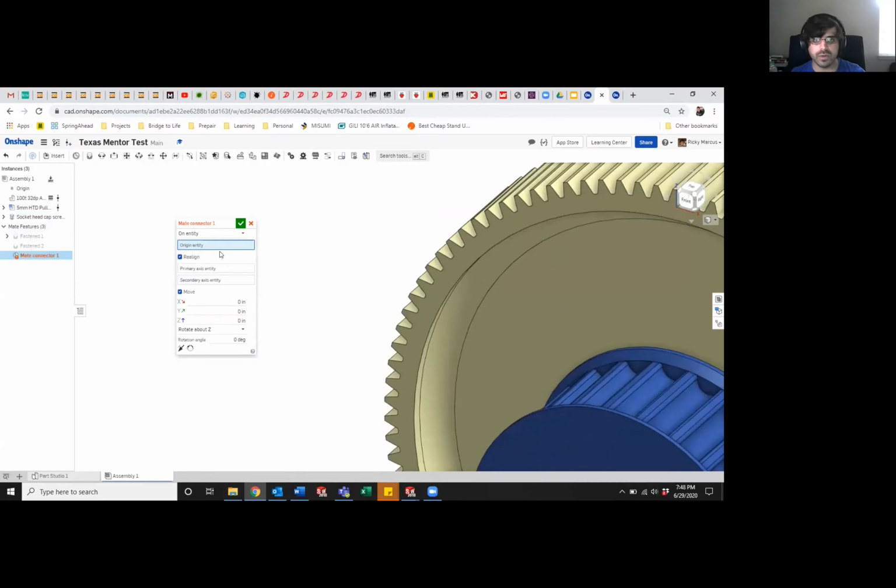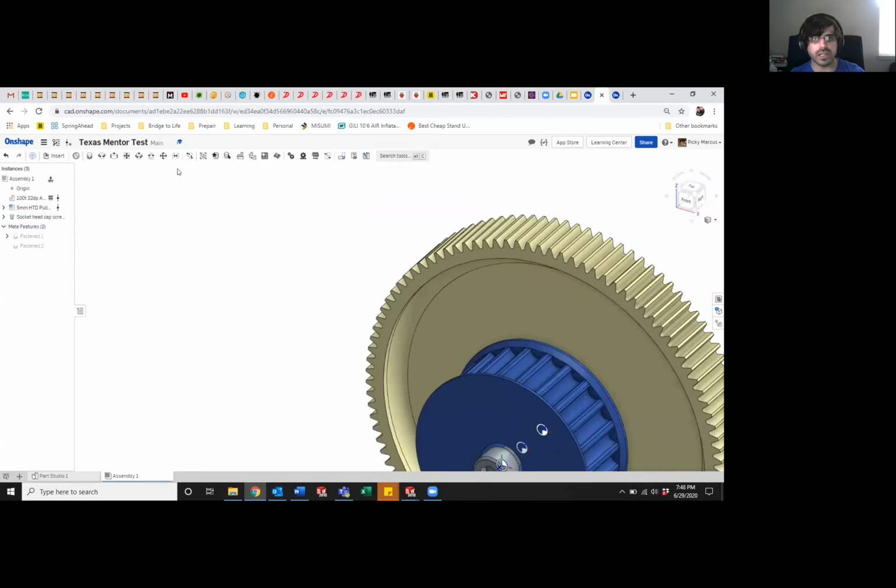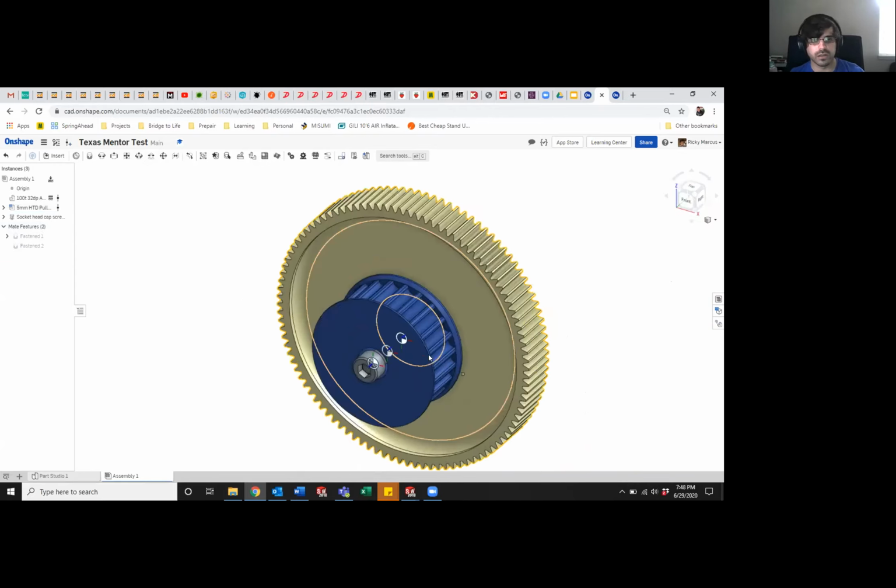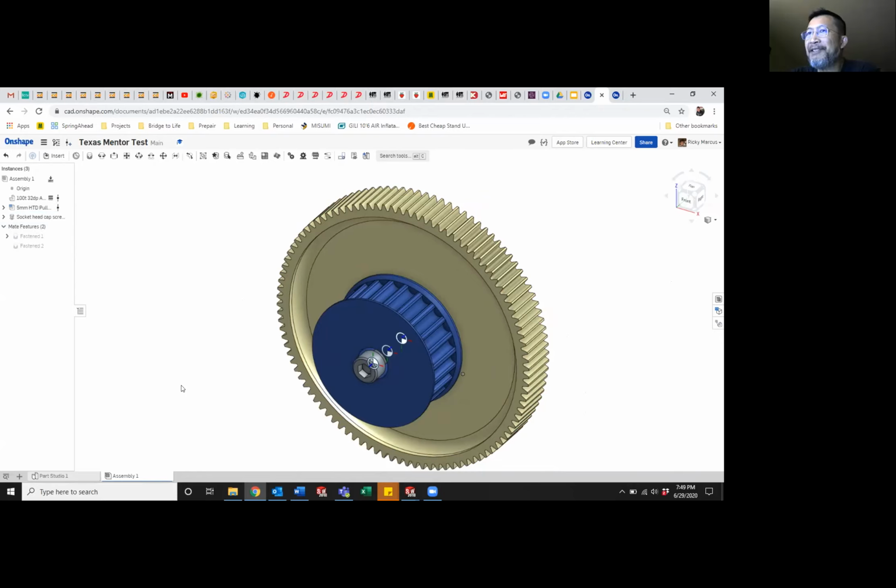And one thing you just have to be aware of, and I think this is just the challenge of switching from something like SolidWorks to Onshape, is if you're really just putting 2 tubes that are going to be fixed together, that should be done in a part studio, not necessarily in an assembly. So just understanding the best workflow for what you're trying to do, and just getting used to it, honestly. Okay, it's good to know I wasn't crazy or missing something.